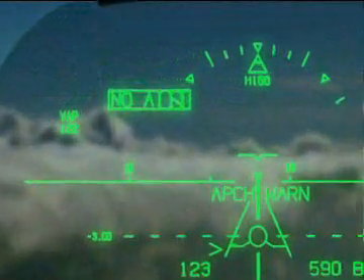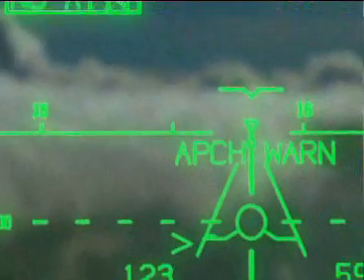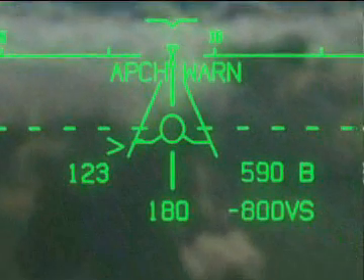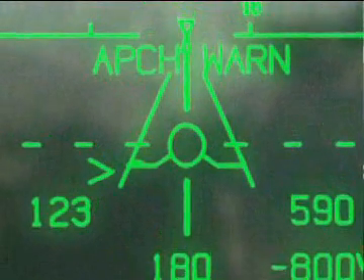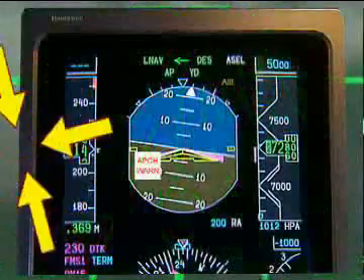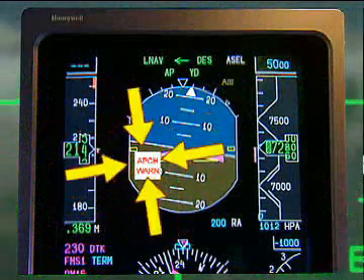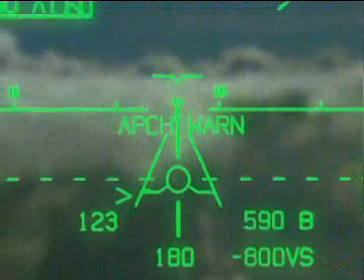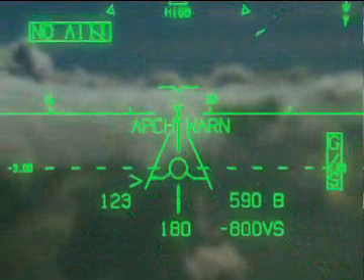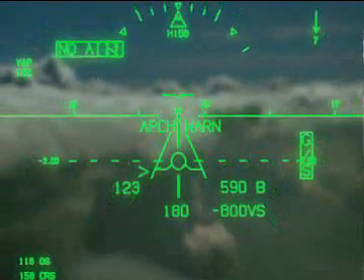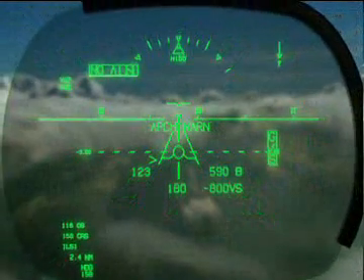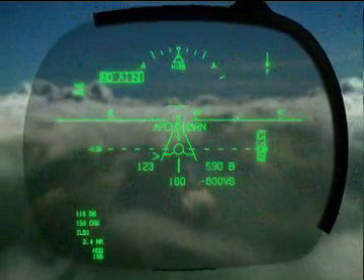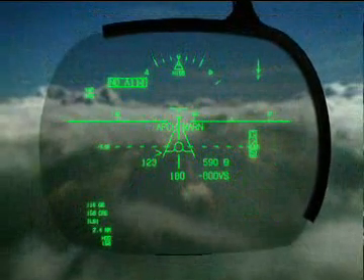If either the A3 capability is lost, no A3 status, or the aircraft approach or flare performance does not ensure a safe touchdown within the required touchdown zone, the HGS provides an approach warning annunciation on the combiner and a red approach warning on the first officer's PFD. An approach out of tolerance condition by itself will result in the approach warning annunciations, but will not cause the loss of the A3 status. In the event of an approach warning indication, the crew will follow approved procedures defined in the operations manual.